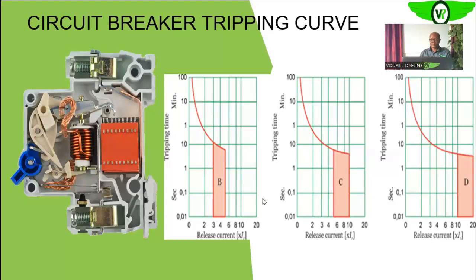So if you take a circuit breaker like a D, you'll see that it will be able to accommodate those 8 times, because of the short time delay up to 10 times the rated current of the circuit breaker, and your equipment will be allowed to come on.